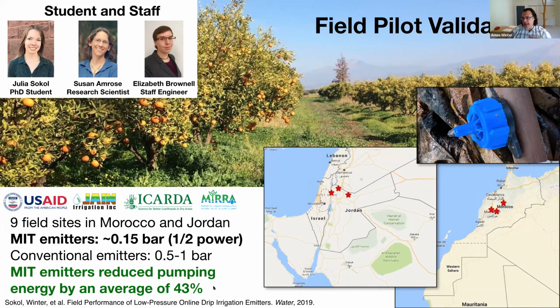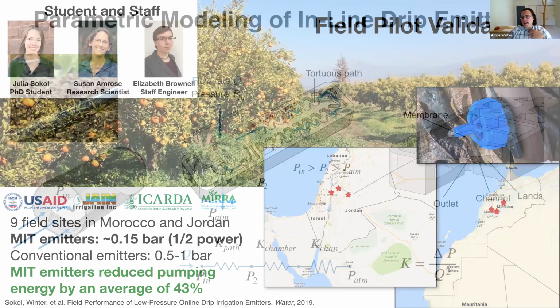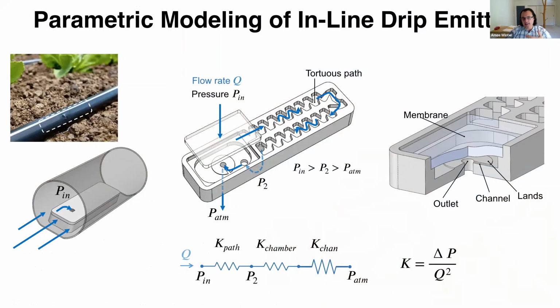about 60% energy reduction. So farmers have been extremely excited about the cost savings they can get from these low pressure drippers. Now we're moving into, and we've made great gains in, making inline drip emitters. You're probably more familiar with these, where the flow control device is mounted within the pipe, and there's a series of flow control features to generate that pressure compensating effect. And it still uses a flexible membrane to do that.